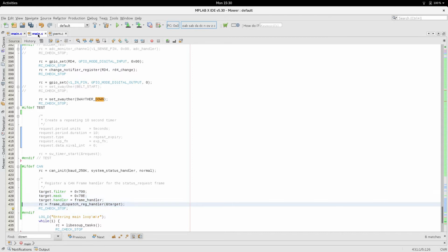So this is the CAN frame that we're interested in. If you look at this, the way we're encoding this, because I've said before, we're not interfacing any other CAN devices. There's no other protocols running, so we can use whatever codes we want. This code has a filter of, if you divide this up into the 11 bits, that's the filter of frames we're interested in, and we've got this pattern of a mask.